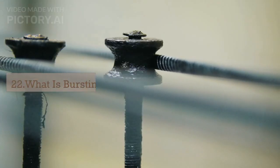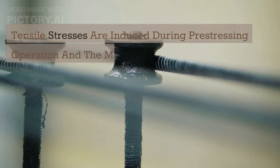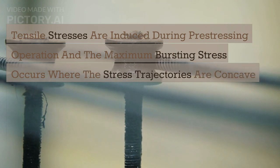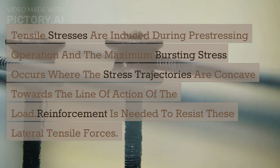22. What is bursting reinforcement? Tensile stresses are induced during pre-stressing operation, and the maximum bursting stress occurs where the stress trajectories are concave towards the line of action of the load. Reinforcement is needed to resist these lateral tensile forces.